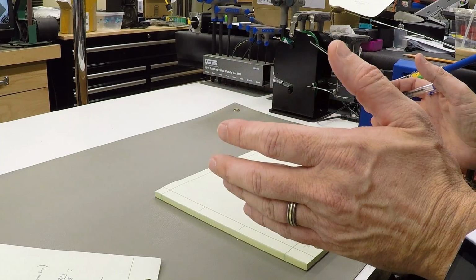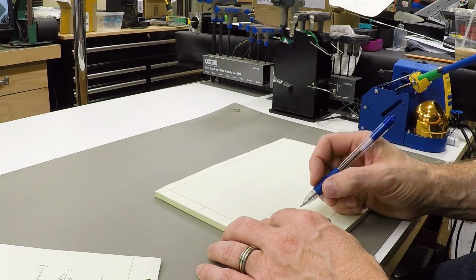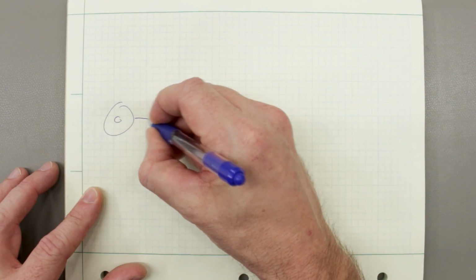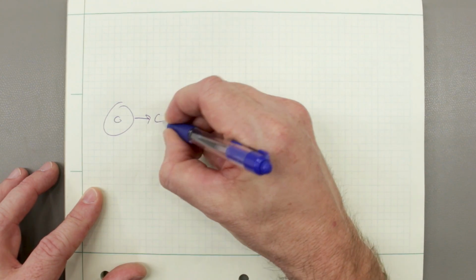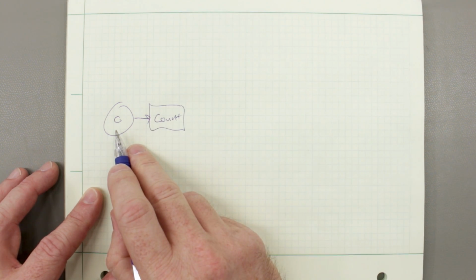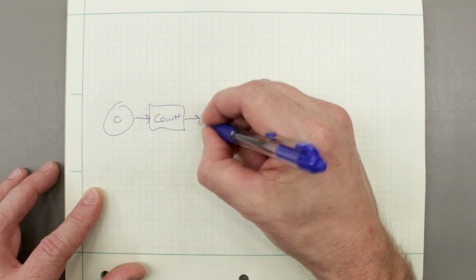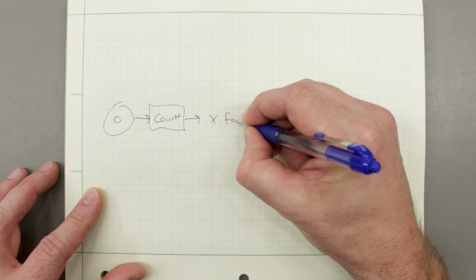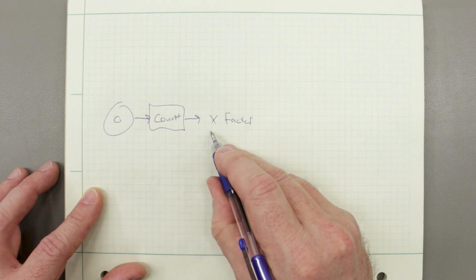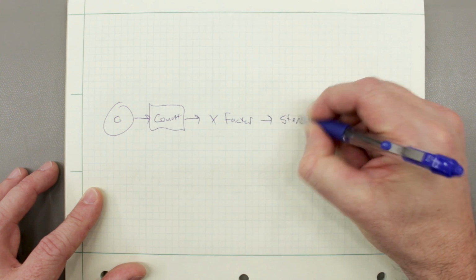So let's talk about what's going on in the software. As you remember, the way the electronic lead screw works is we have an encoder, and that is updating a count. And this is a count of quadrature edges that are coming in from the encoder. This is managed in hardware. Then we take that count and we multiply it by some factor, and that gives us a desired number of steps.